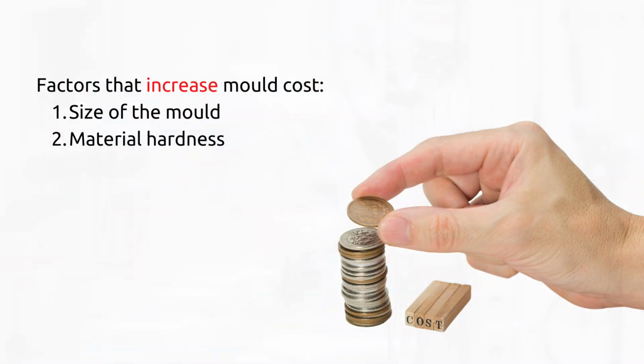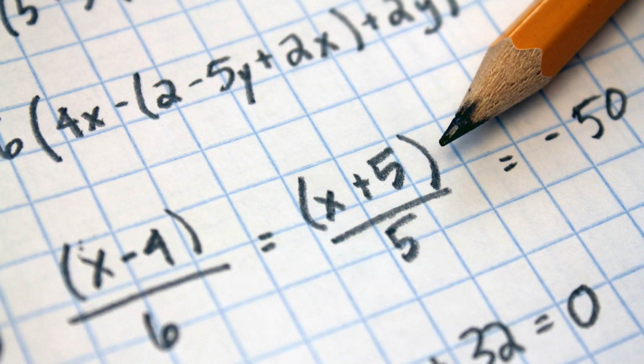On the other hand, an aluminum mold will be easier to mill and therefore less expensive, but it will also break down quicker and be able to produce fewer parts in the end. Deciding which material option will be best for you really becomes a math exercise that is influenced a lot by what budget you have up front and also how many units you plan to produce.